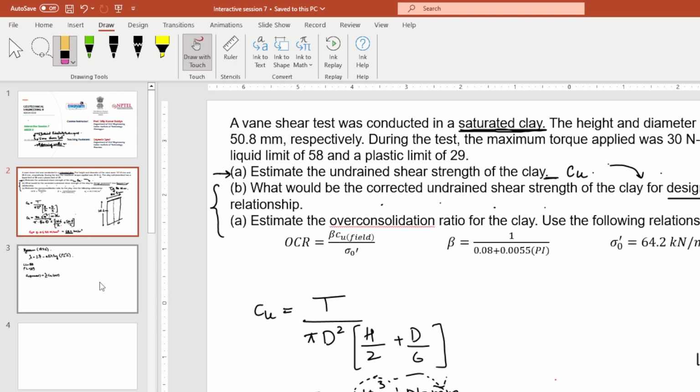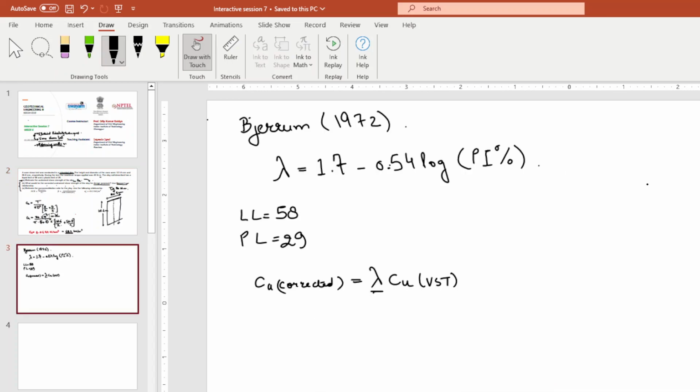See, what will you do for design? You will have a footing, okay? Then you will apply qu equals cNc, for example, for a clayey soil. Here c is directly proportional. Nc will be 9, for example. 9c will be your ultimate load. If you apply 9 into 62 or 9 into 40, you see how the ultimate load will change based on Cu.